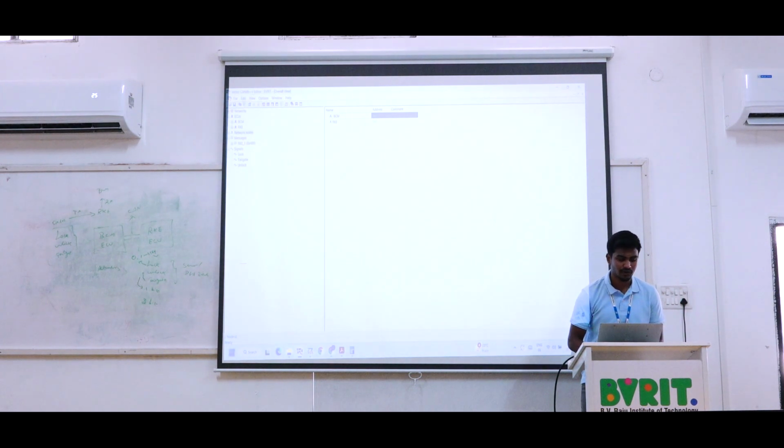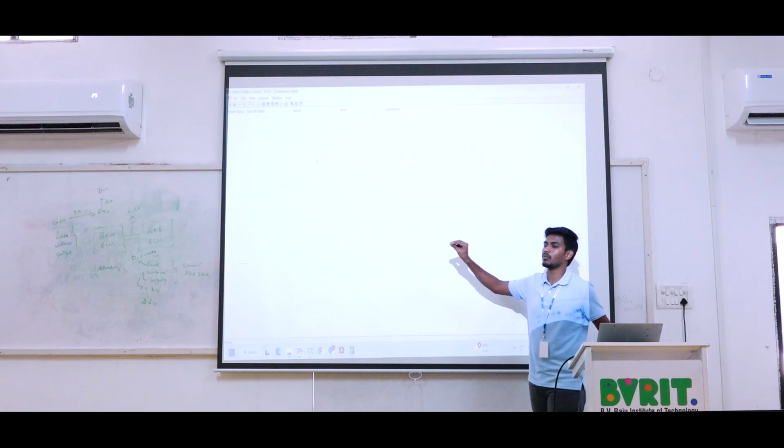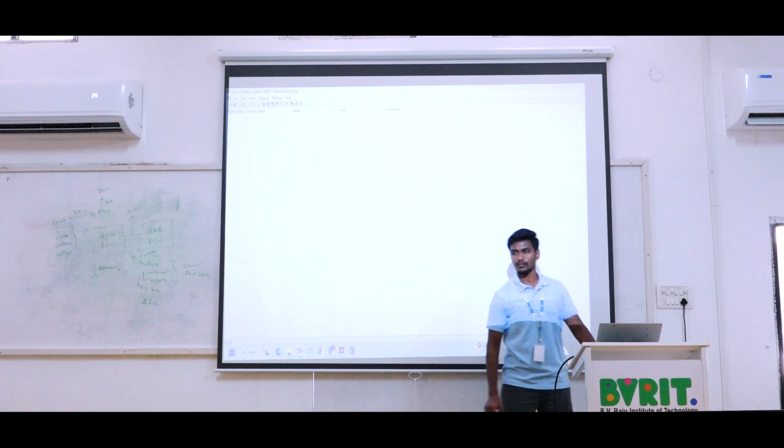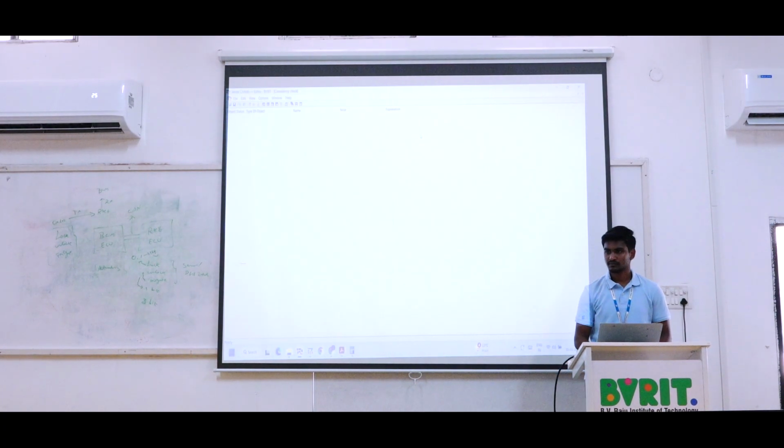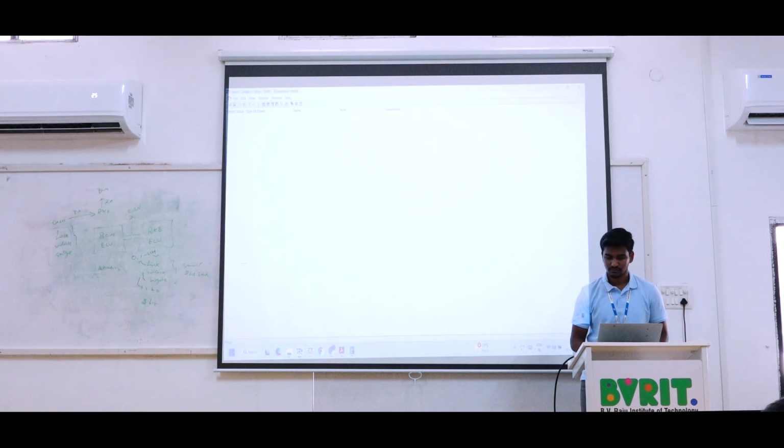Now we can go to File, top of the file, Consistency Check. Now this column will be empty. Whenever we get this column empty, we will have the proper CAN database. Is consistency check possible, sir? If there is any error, the consistency check will show what the error is. You can take 5 minutes and then come back.